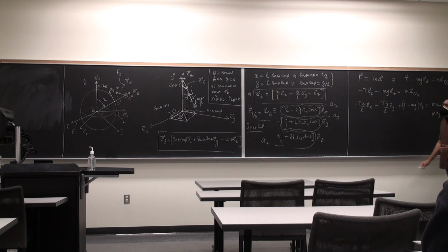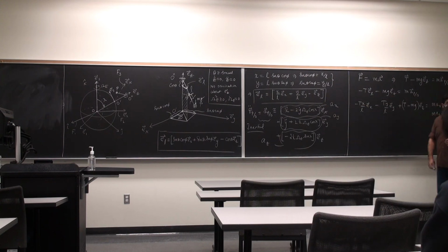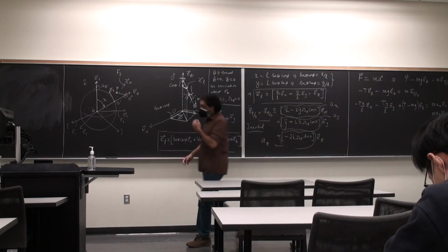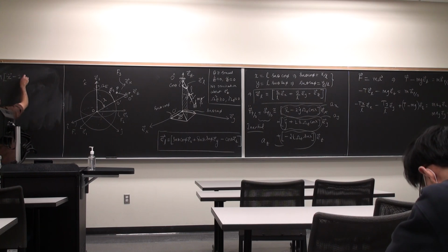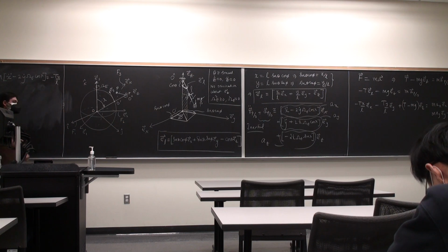And this is one reason why we say that the terms y dot, x dot are all bounded. They don't grow rapidly with time. So we're going to get rid of that and then just do force balance. Mass times acceleration in the x direction, I'm going to write it out: m times x double dot minus 2 y dot omega e cosine lambda is minus T x by L. Just mass times acceleration in each direction.